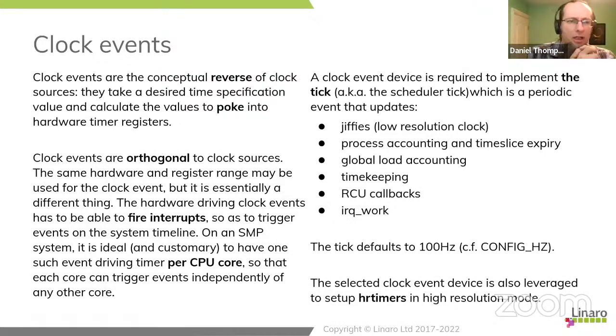Clock events are, I don't know if it's the reverse of clock sources, but they do the opposite of a clock source in that instead of free running and counting time, they take a time that you want to reach and calculate the values that you poke into hardware timers to arrange for the event to happen at a given point in the future. But like I say, it's quite common for clock events and clock sources to use the same hardware, but they don't have to. You can use a countdown timer as your clock event and a free running timer as your clock source.